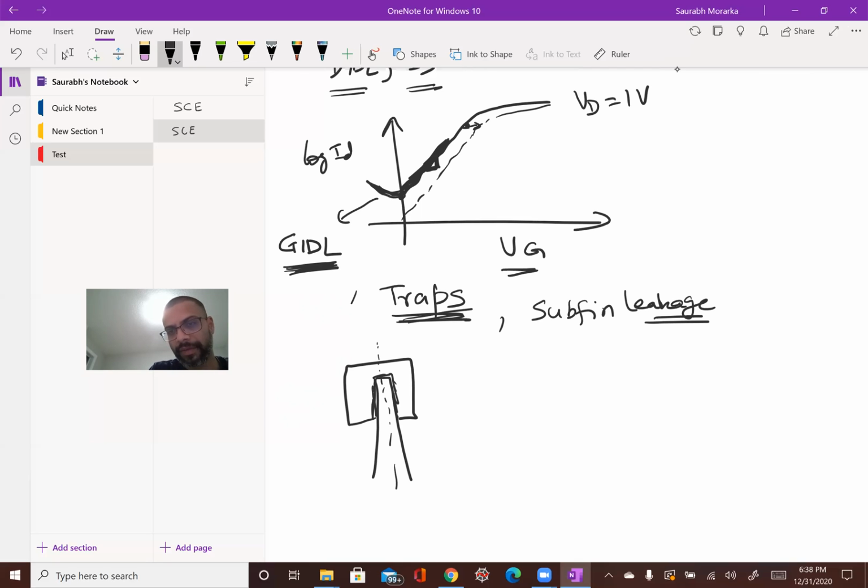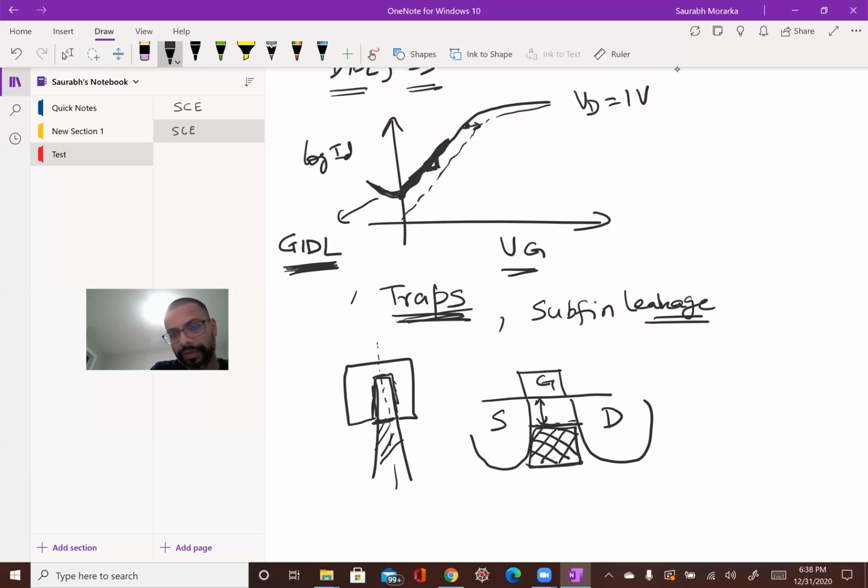So if I were to take a cross section of this picture, what I would see is the gate looks like here, the source would look like here on this side, the drain would be here, this would be the gate. This is the region which is controlled by the gate because the gate is wrapping around the fin. And this region is the part which is, so let me draw it here, would be this one, right? Now, think about how the gate is able to control this region very well because it being a FinFET device, and the source and the drain leakage is very well controlled.